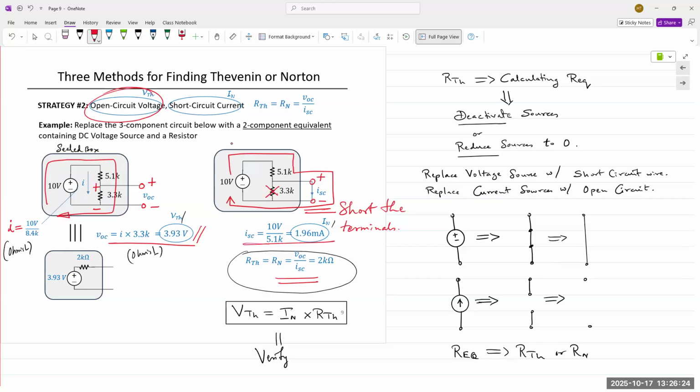You'll encounter these often. So if you have a short circuit anywhere in your circuit, anything that is in between those two nodes is effectively removed from the circuit. Okay, so that's an important concept. All right, let me know if anyone has any questions. Does that make sense to everyone? Yes.